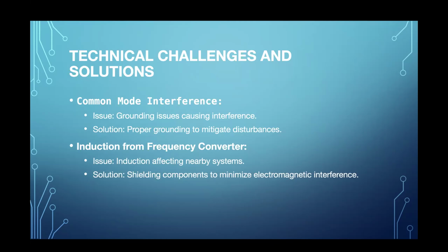If you have a switching power supply, you will get a big problem with voltage between the earth and ground. So in this case, you have to connect the ground from the power supply to the earth. Otherwise, you could get 90 or hundreds of volts, and this will damage the Raspberry Pi immediately if you touch it.